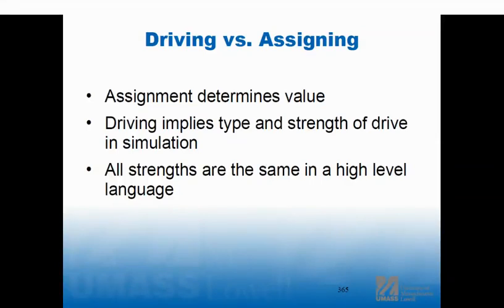And the idea there is, in ASIC design, you have to specifically determine for every one of those what cell you're going to use for the I/O. Maybe a bunch have the same, but you have to think about every one. And if you go to a different ASIC or something changes physically, you don't want to change that core logic. You just want to change that I/O piece. So it's very common to have the top level of the chip, and in it are the I/O pads in one block, one module, I should say, and then the other module is the top level of your logic.